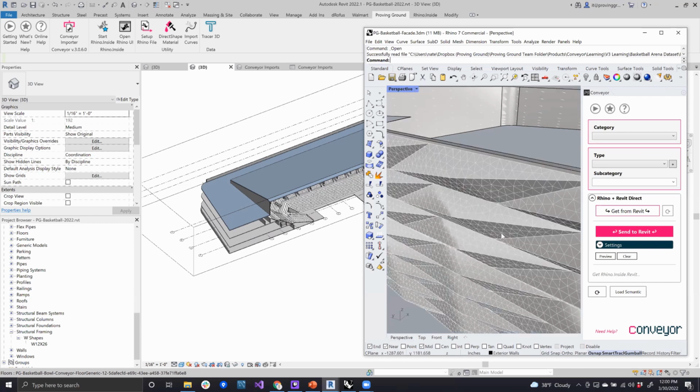And when you bring a mesh over using a more conventional export, like a DWG or a DXF, and then you import it into Revit, you end up with all the triangulation, and it's not useful for anything other than maybe some level of clash detection or general coordination. It doesn't look good in your documentation.